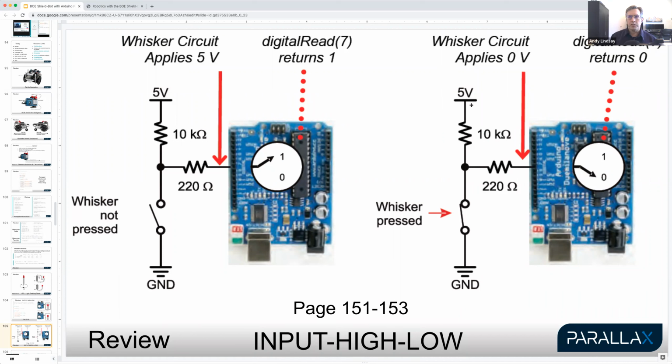And for those interested in the electric current properties, a little bit of current flows this way at the same time. And also this kind of thing is explained. This is called a pull-up resistor, and either a pull-up or pull-down resistor is required in circuits that measure contact like this, because if you simply made contact, sure, the pin might see ground.